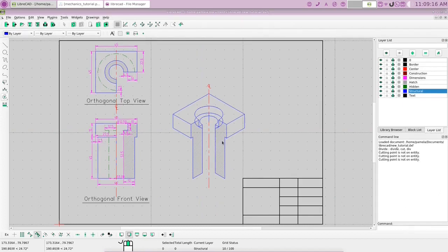Okay, so now we have to cut this bottom circle, because a portion of this is hidden. So if you choose divide and choose snap on entity, and it says here specify the entity, that would be this one, and then snap on that entity, click, and do the same on the other side here, and you will have left these bits of line in here that you cannot really see from this view.